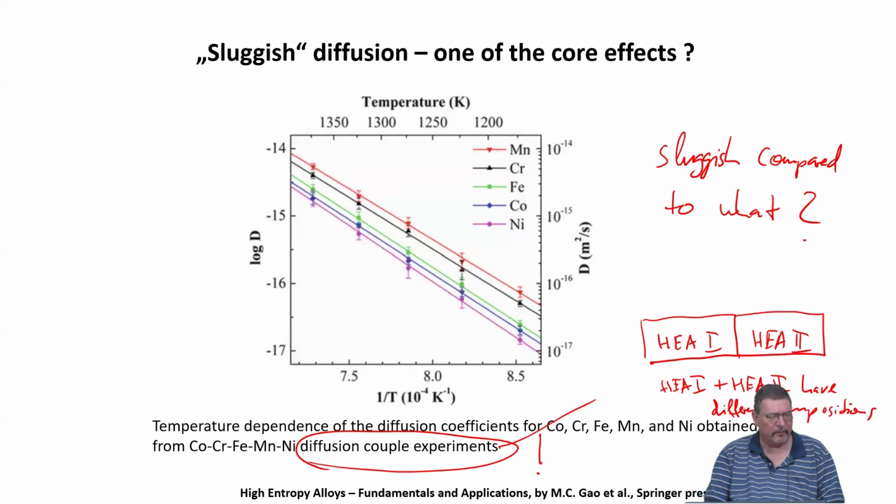So we have an interdiffusion flux of elements, driven by chemical diffusion, by the gradient in chemical potential. This is not self-diffusion, because there is an additional force term, in terms of non-equilibrium thermodynamics, given by the concentration gradient, or the gradient in chemical potential, to be more accurate.